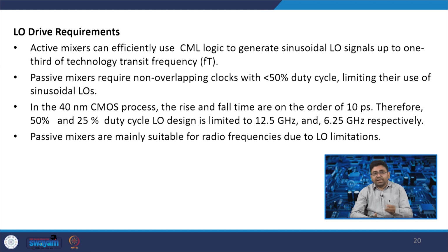But if we want better parameters and design, then the 25% duty cycle is a must, and to make that possible we need to go for lower node technology, 22 nanometer or lower, if we want to achieve high frequency. Otherwise we can use the 50% duty cycle. So this is the LO requirement, and LO generation is important in passive mixer design.